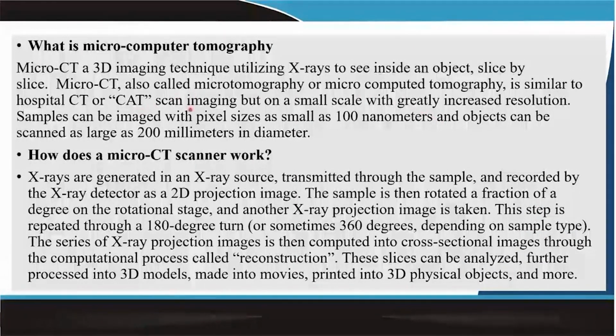Finally, micro computed tomography is based on the same concept as radiography, but here you use X-ray as a source with very low energy. The X-ray is scanned over the surface, and you can detect the defects in a slice by slice fashion, and with the help of CAD modeling, you finally observe 3D images of the defects or of the surface and location of the defects. Everything is possible with this computer tomography technique.